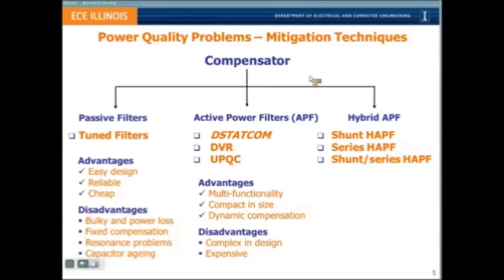Expensive, because of the reason, but now it is really not, because we have switching devices which can handle considerable voltage and current ratings, but they are still cheap. I mean, we can see evolution of IGBTs over time, which are proving to be quite cheap. For example, there is an IGBT from Mitsubishi, which is CT60AM18F, which costs about $4, but has a capacity of about 700 volts in withstand voltage and 60 amperes. So they are not actually expensive.